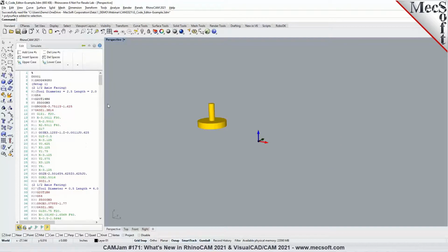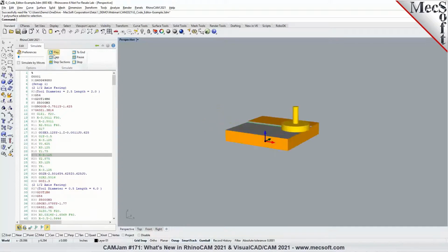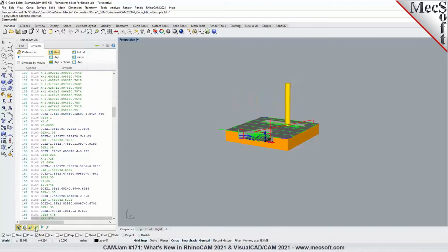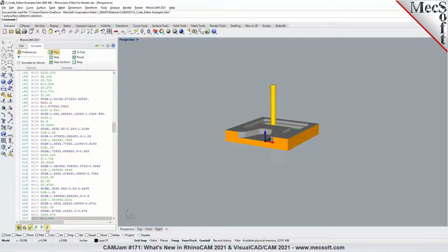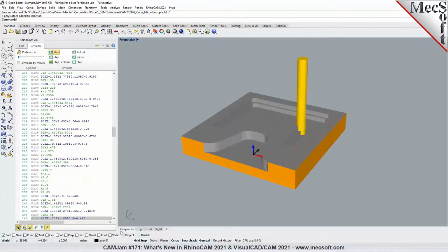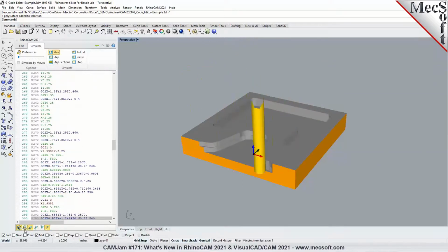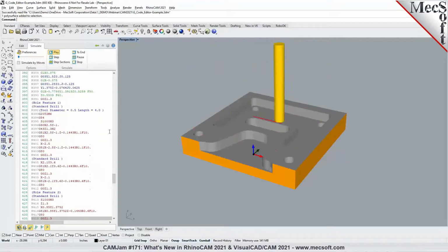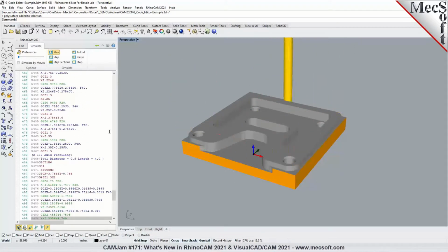in the G-code editor module, which was not available in our previous release. As you go to the Simulate tab and hit play to run a simulation, you now have the option to hide or show the toolpath as you're simulating. You also have the option to enable the follow mode segment toolpath display as well. So these display toolpath toggles are available in the G-code editor module as well. You can hide the part and the stock visibility. You can toggle them as you're simulating or editing the toolpaths in the G-code editor module.